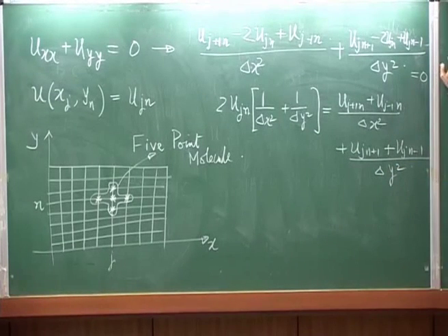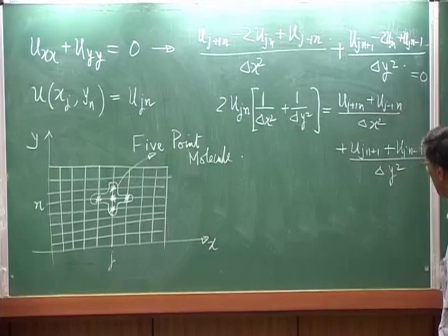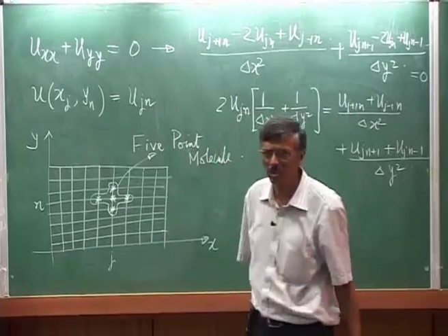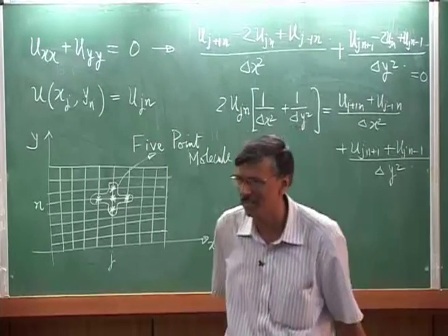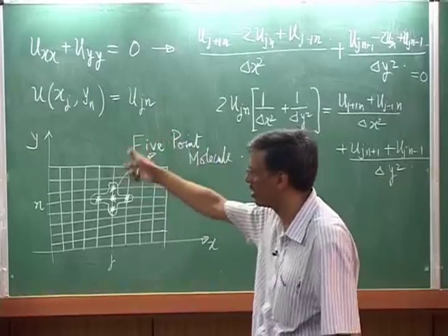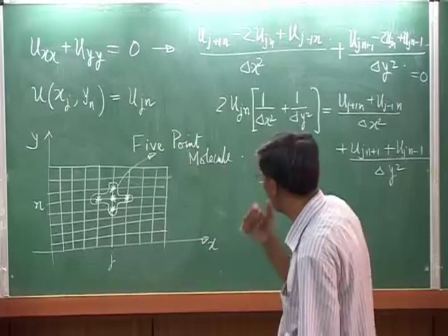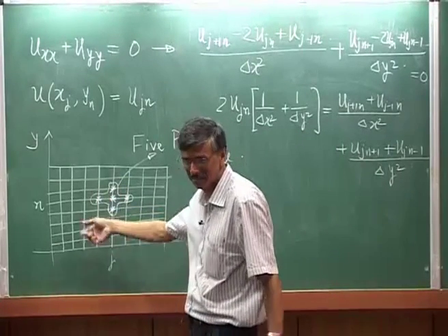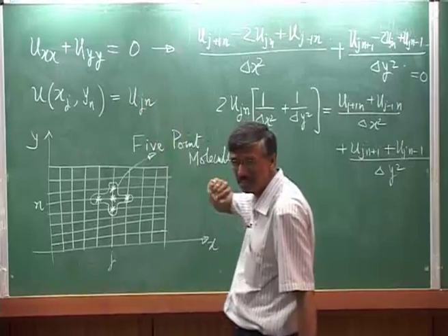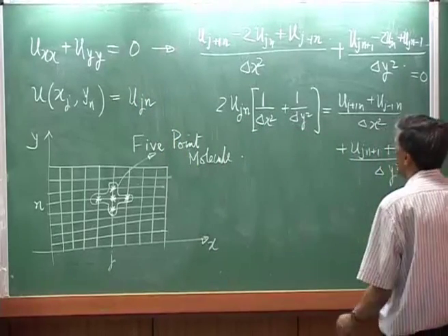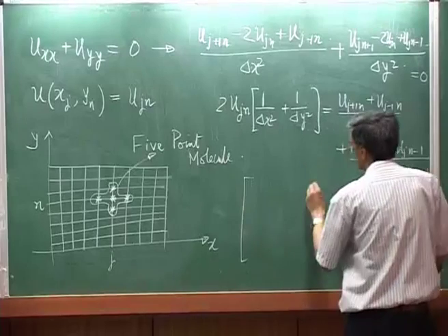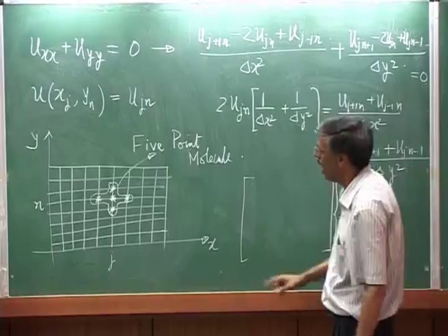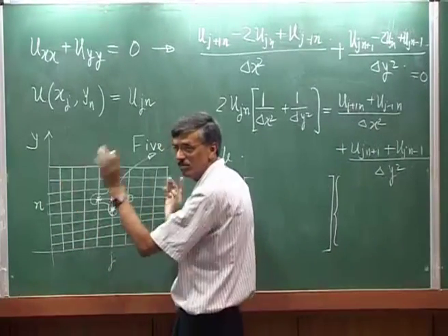Look, the way this equation is written here, if I were to stack the unknowns, now this is an elliptic problem. So, it is a boundary value problem. So, I can't do any of my other tricks that we have used in the heat equation or used in the boundary layer equation. What will happen? Each point will be influenced by the 4 neighbors for this kind of discretization. If I write down all the unknowns, so what I will require is boundary conditions here.